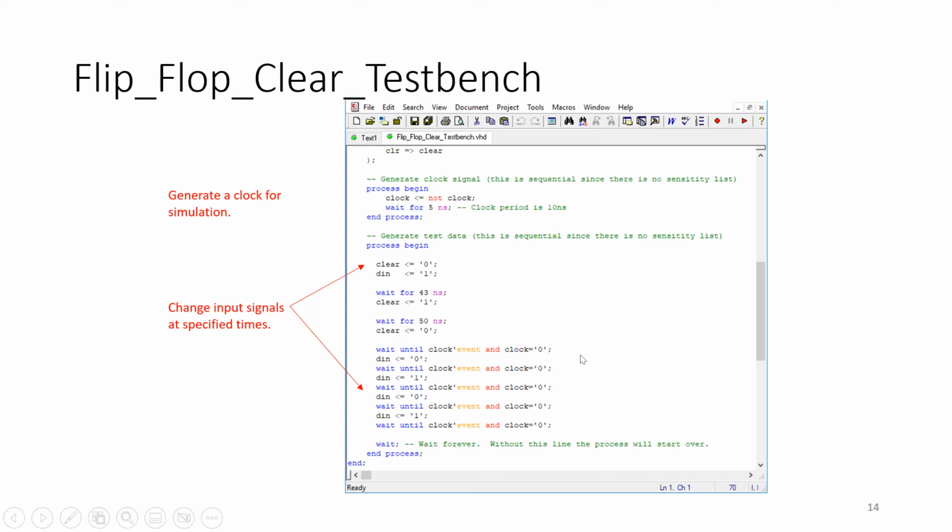That specifies that we are speaking about a falling edge. In this case, let D in be 0. I wait again until there is an event, a falling edge, make D in equal 1, and so on.